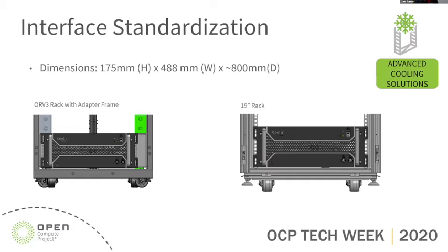The RPU has been designed to fit within 4U of standard 19-inch EIA rack, such as the OCP Project Olympus rack. As the volumetrics are larger in the open rack architecture, an adapter frame has been designed to allow for standardization of the chassis components.